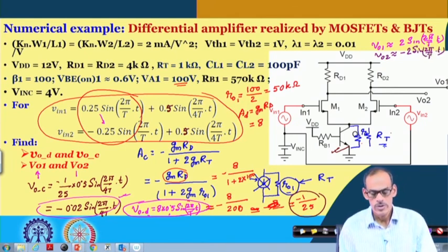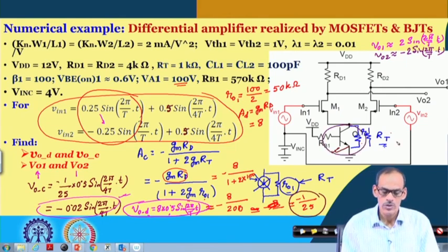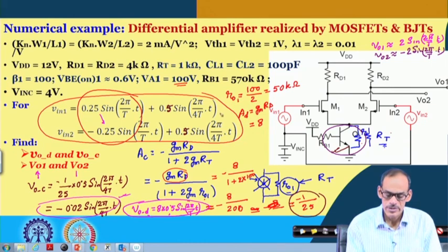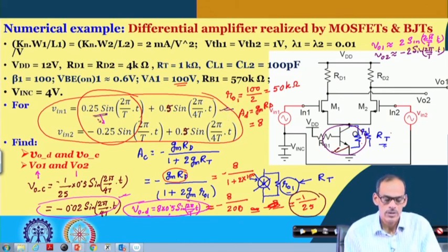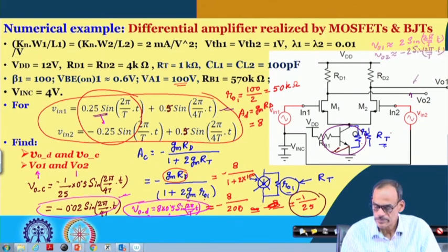So, to summarize, replacing this tail is also helping to suppress this common mode part and still maintaining the differential signal quite prominent. Particularly if you observe the output, the signals there are almost complementary to each other.